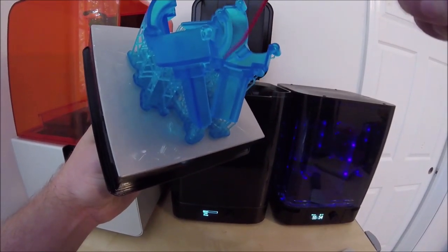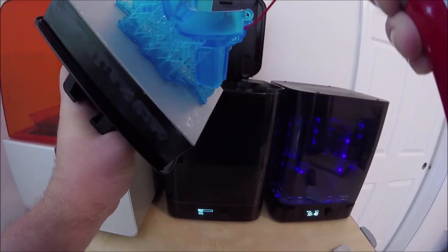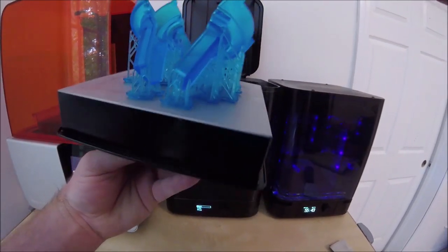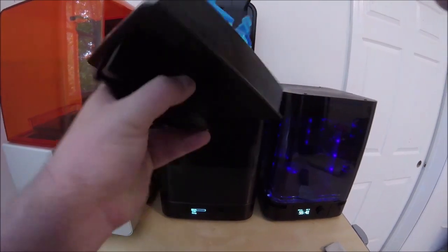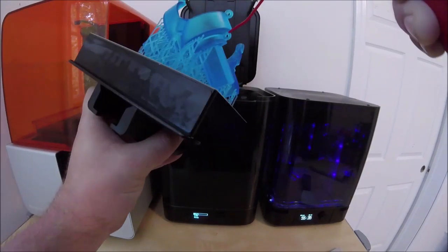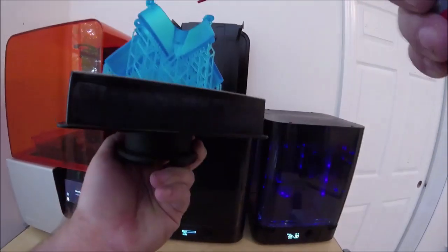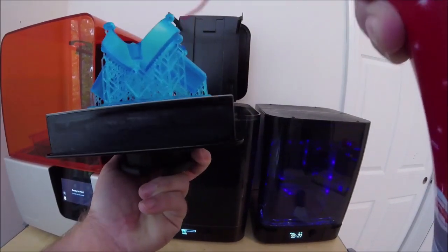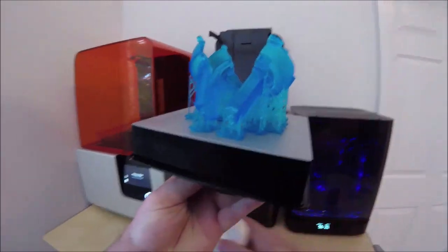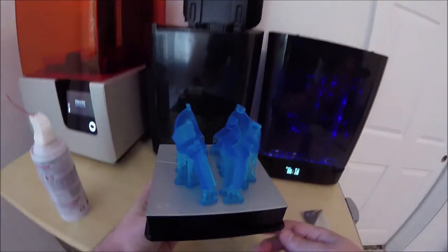So we'll just go ahead and give a little spray in those sort of areas, maybe down in some of these holes. So make sure we've got all the alcohol out of all the holes. Any tight corners like this can sort of trap a little alcohol, and you can see it probably spraying out of there right now. So I just like to go around all these sections, just make sure I'm not leaving any areas where there's liquid alcohol and resin, because once that goes into Form Cure, that resin and alcohol will actually cure in place. So we want to make sure we get it off there and it's dry first.